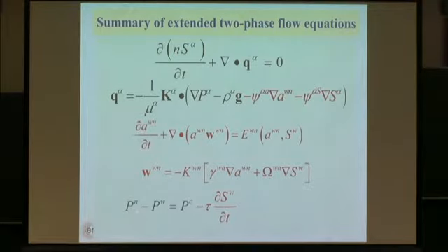What we also find is that the pressure difference between the phases is not equal to capillary pressure. There is a dynamic term. And this now accounts for all those capillary pressure curves I showed you. I said it's a mess. Now we have a more complex formula. And the capillary pressure is not just a function of saturation, but also interfacial area. It's the distribution of phases.